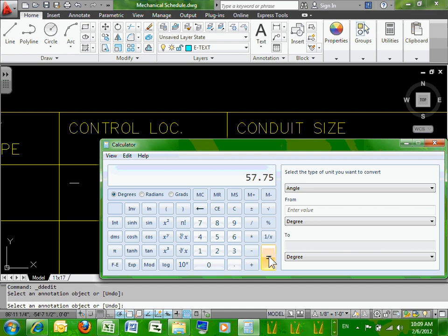And if you go to NEC, what would that give you? These are motors, so you're going to go to the 75-degree column for all motors. So this is going to give you number 8. Can anybody give me number 8? If you go to 75-degree, and I'm looking at 57, 60, number 6 actually.